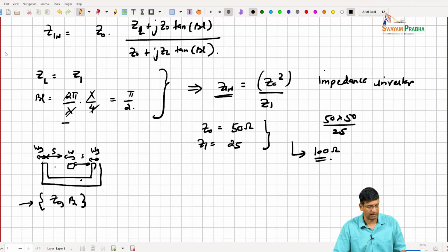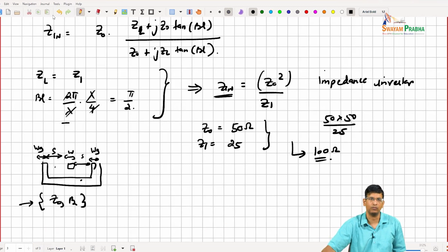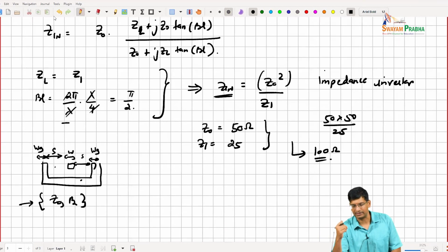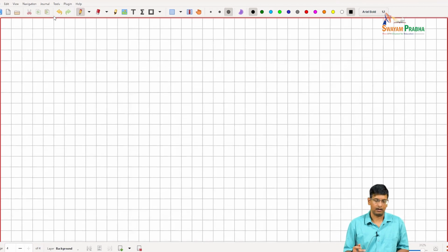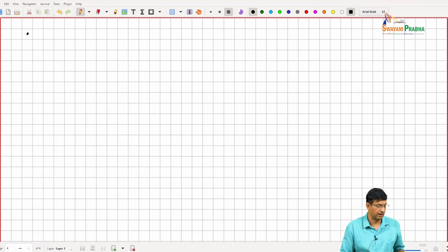There will be, I think, a somewhat justified statement that transmission line based circuits at millimeter wave can occupy a little bit more area than if we use L's and C's, right? But you can also quite aggressively meander the transmission lines. We will see some examples of that as we continue. One complaint, as I mentioned, is about the fact that T-line based circuits can occupy an increased area, right?